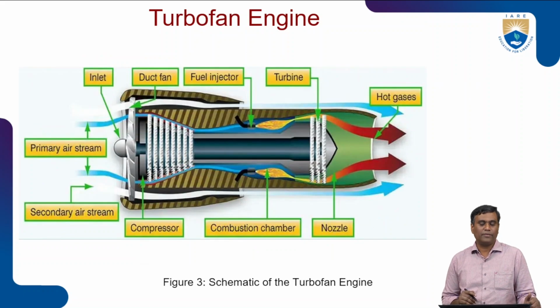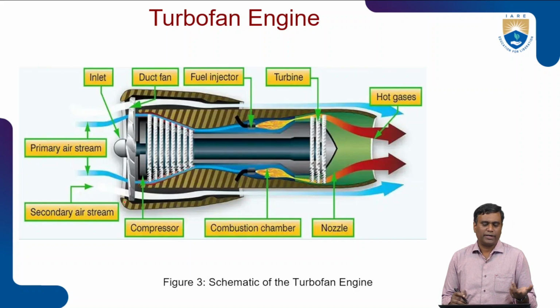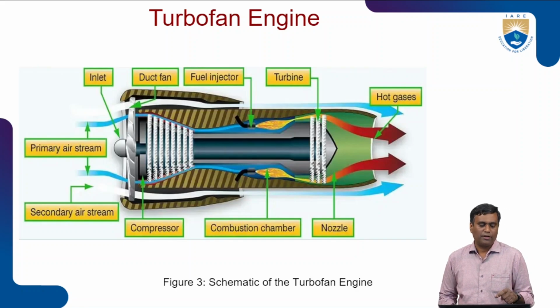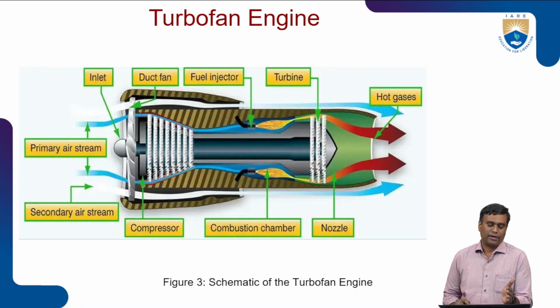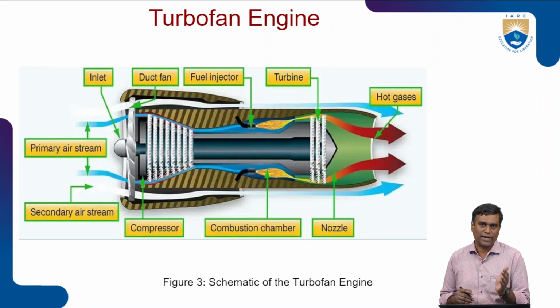In case of turbofan, we have seen already, almost all components remain the same as the gas generator, except the fan. Few are ducted and few are non-ducted fans, and few are located before the compressor, and few at the aft of the exhaust nozzle also. That type also is there. Fans at the front of the engine, fans at the back of the engine also are possible.